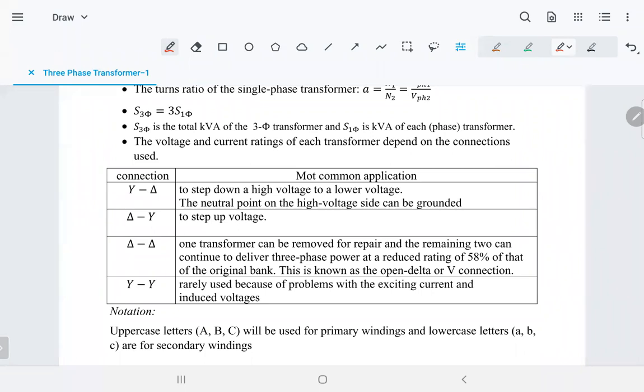Then when we go to the consumer, the voltage of the transmission line is high, 11 kilovolt. It's impossible to get 11 kilovolt to your home or to the building. So they have to lower it. So it goes to a place called a substation. This substation has 3-phase transformers with protection, breakers, and things like that. The transformer lowers the voltage from high voltage to low voltage so we can use it, because it's already transmitted. So now we want to use it. You don't use kilovolts, you use a normal voltage like 110 volt single phase, and then square root of 3, that would be like 208 line voltage as you have in the lab. So that's the main transformer used in this application.